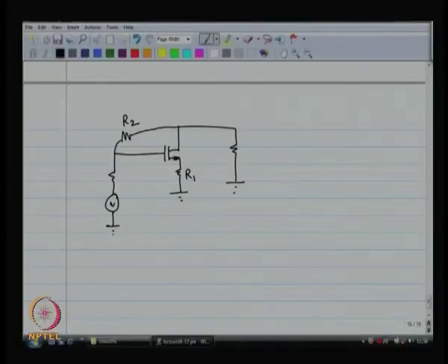When you buy an oscilloscope, let us say it is a 1 gigahertz oscilloscope, it should be able to process all frequencies starting from 0 all the way to 1 gigahertz. So, that is what a wideband amplifier does. Okay. 1 gigahertz oscilloscope does not process only signals at 1 gigahertz, it has to process all frequencies between 0 and 1 gigahertz, right. So, it is a wideband system, and this particular shunt series amplifier, for example, is used a lot of times as the input front end for an oscilloscope.